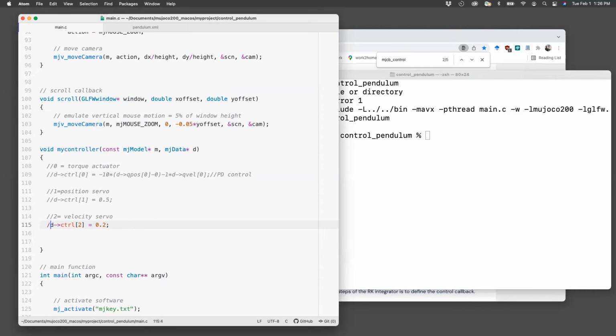Okay, so what we have seen so far is torque control, position control, velocity control. You could also do something which people do when they want to check controllers. That is, they want to introduce noise and then control based on sensors. So we'll do that as step 2. What I'm going to do is define a block for sensors.